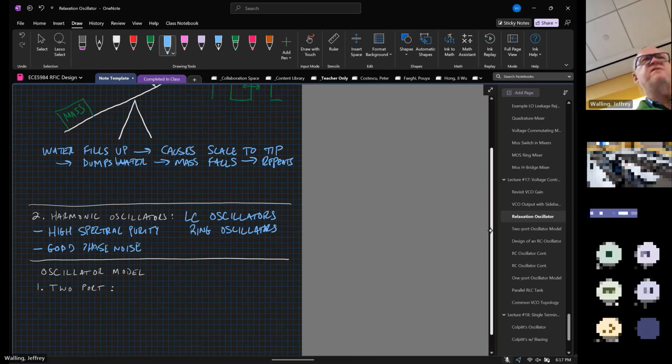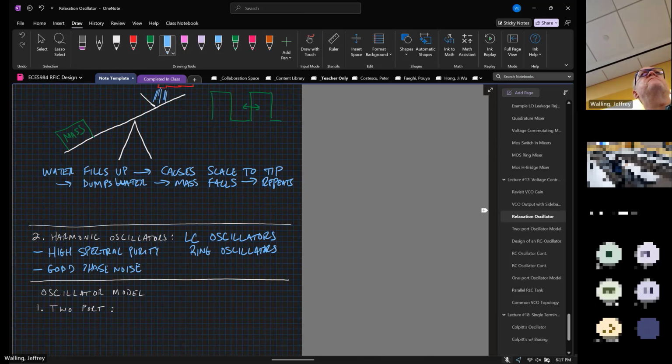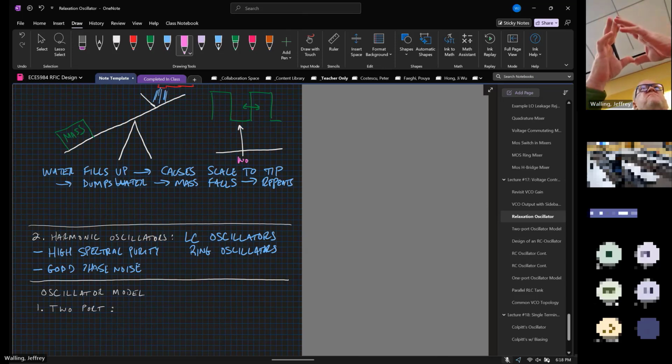I actually don't know that we talked about phase noise yet. For the time being, just know that when we make an oscillator, let's say that this is our center frequency, we'd ideally like the signal of the oscillator in the frequency domain to look like an impulse, right? But in reality, because of the uncertainty of when the edge crossing happens, the energy is going to be spread out from the center frequency of oscillation, and it'll be modulating the VCO. That's where that omega m shows up.